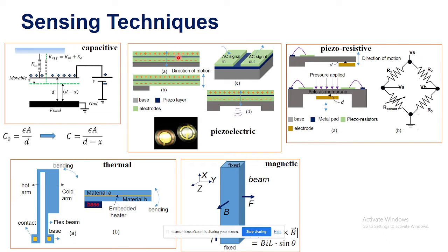So let's see how this will work as a sensor. When we apply a voltage difference between the top and the bottom electrode, electric charges of opposite polarities are created, as indicated here. We see positive charges and negative charges. When we apply a mechanical force, let's say we press this material, charges are produced. Again, we can use electronic circuits for charge to voltage conversion.